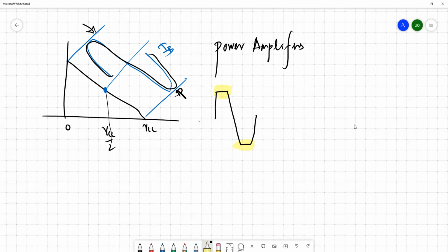If you input a base current like this, having a higher span than the given spec, once you move the Q point to here, it jumps to saturation, and with this kind of external base current, it jumps to cutoff.